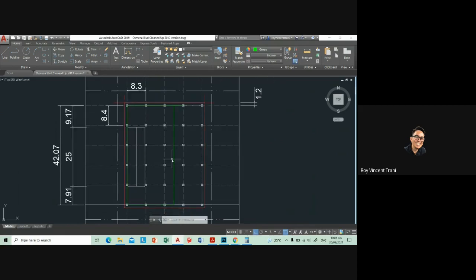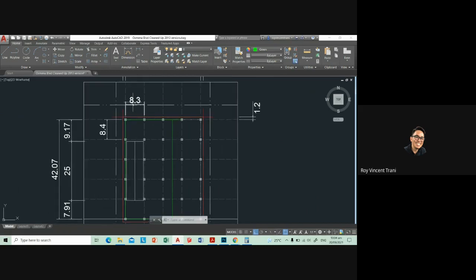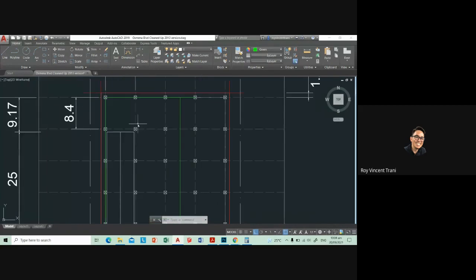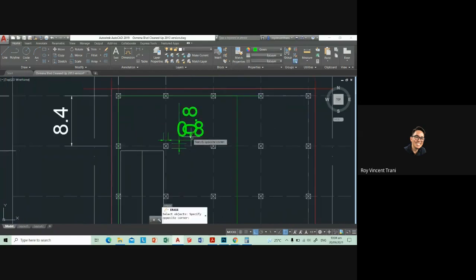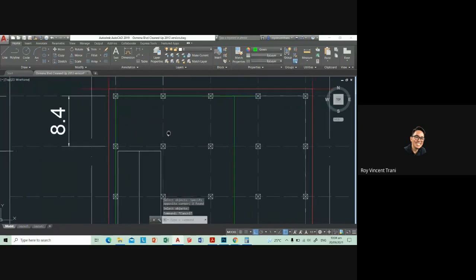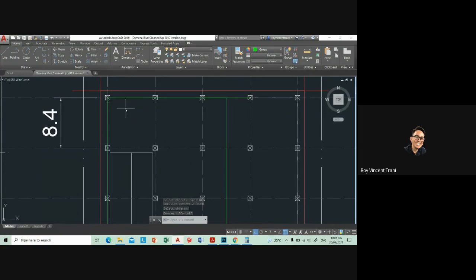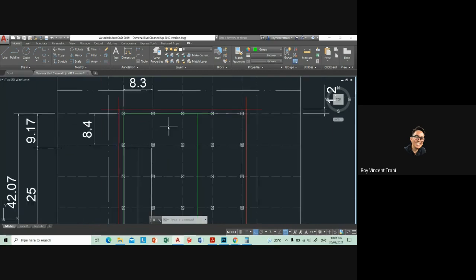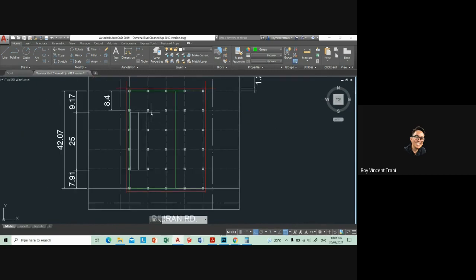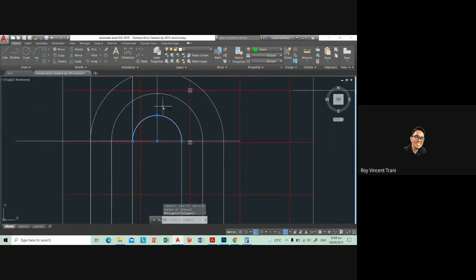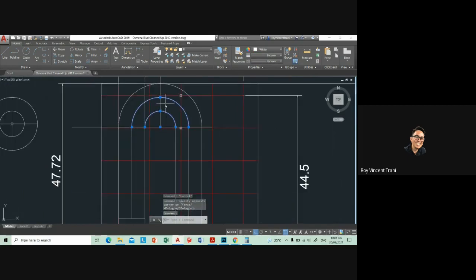So with this setup, you can sort of find the ramp fits. We have a typical, as much as possible regular columnation, 8.3 by 8.4 grid, with columns that are 0.8 by 0.8. That's just a very simple rule of thumb that your column dimensions should be 10% of the column span, the length between columns.